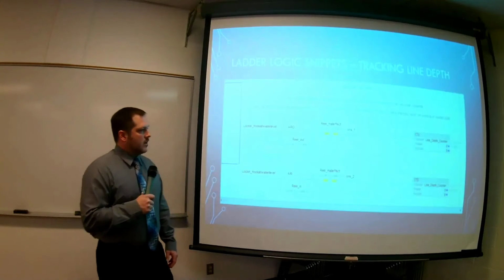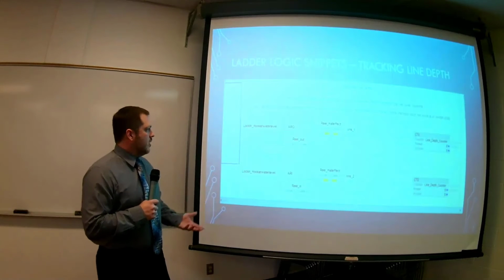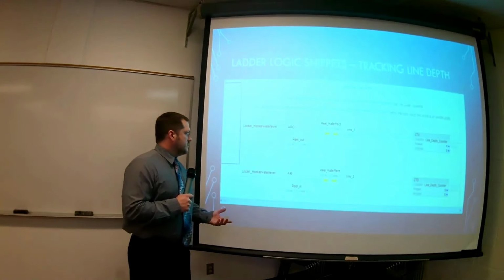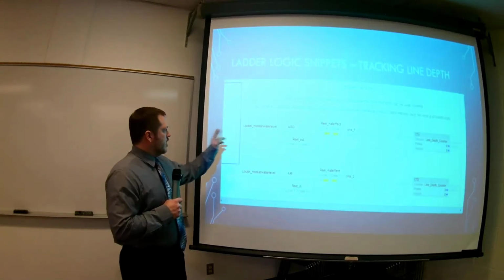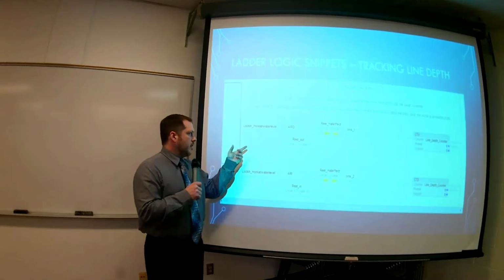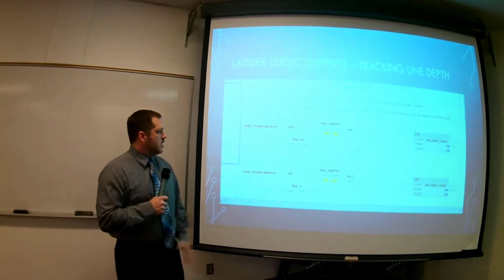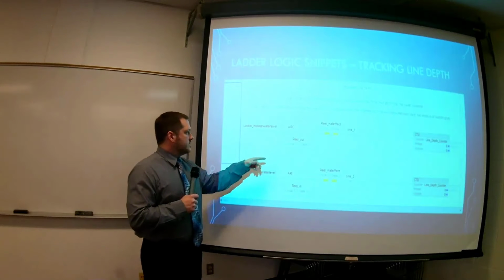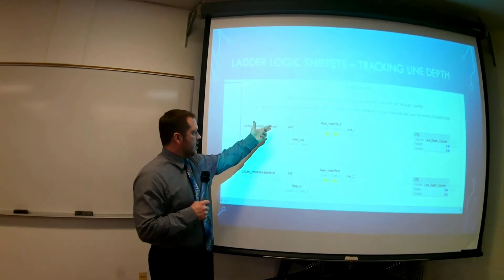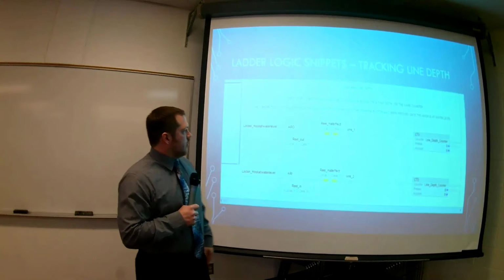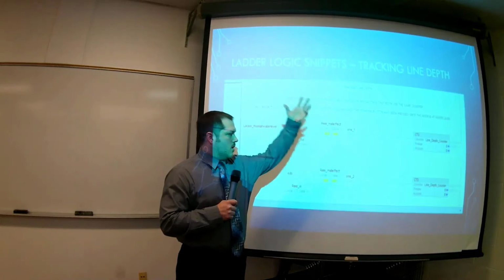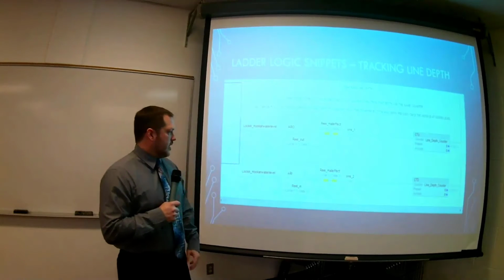So here are the counters. We're counting up and down pulses with the Hall effect sensors. We have our lock-in, which is the confirm button that we push when we're at the water level. Then as long as we're reeling out, with automatic reel out and reel in, we're going to count pulses. So count up and then count down, which are going to keep track of our depth.